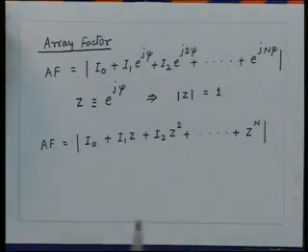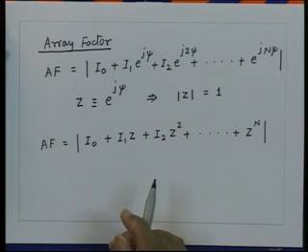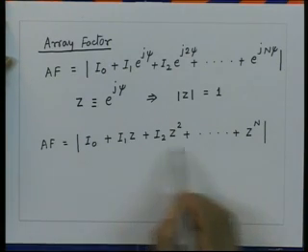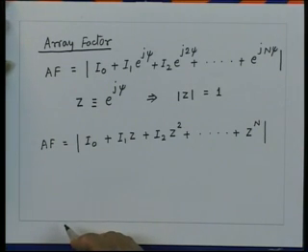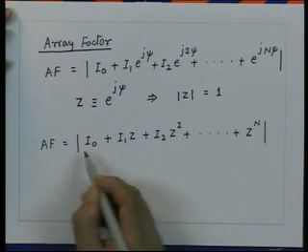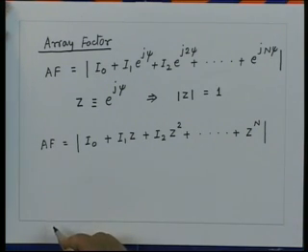So, now in general we can say that the radiation pattern of an antenna for which the inter element spacing is the same can be represented by a polynomial of z. Now, as we know, a polynomial of nth degree has n roots in the complex plane. So, essentially this polynomial will have n roots in the complex plane.